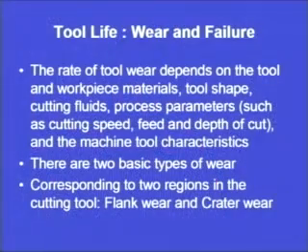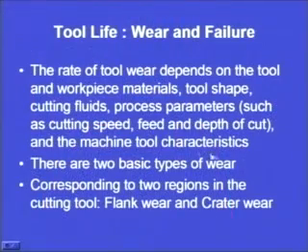Moreover, it will depend upon the process parameters also. Now, what are the different process parameters? These are cutting speed, feed and depth of cut. If we are machining at a very high speed, the chances are that the tool wear may be more. And if we are machining at very small speeds, then also there are chances. It depends on a number of parameters. It is not that this always happens, but mostly if the speed is very high, there are chances that the tool wear will be more. Then, besides the parameters we have seen, cutting speed, feed and depth of cut, there are the machine tool characteristics. So, the tool wear will also depend upon the machine tool characteristics. What are the important machine tool characteristics?